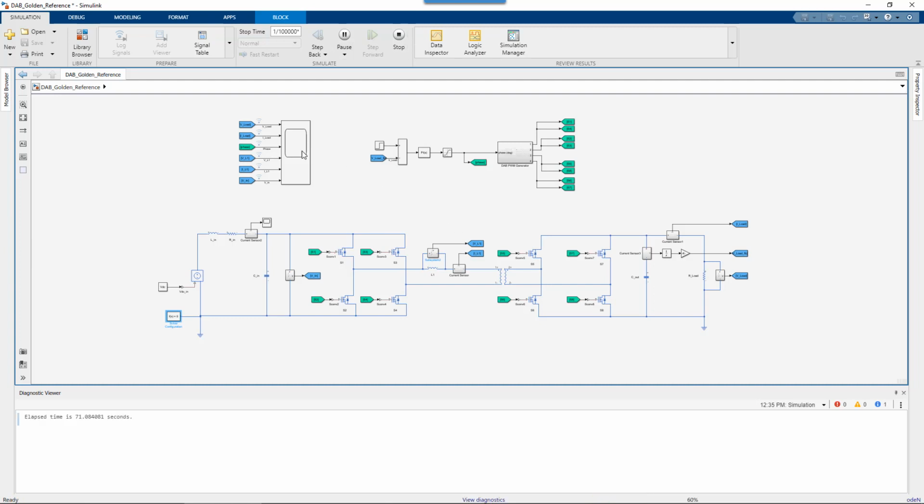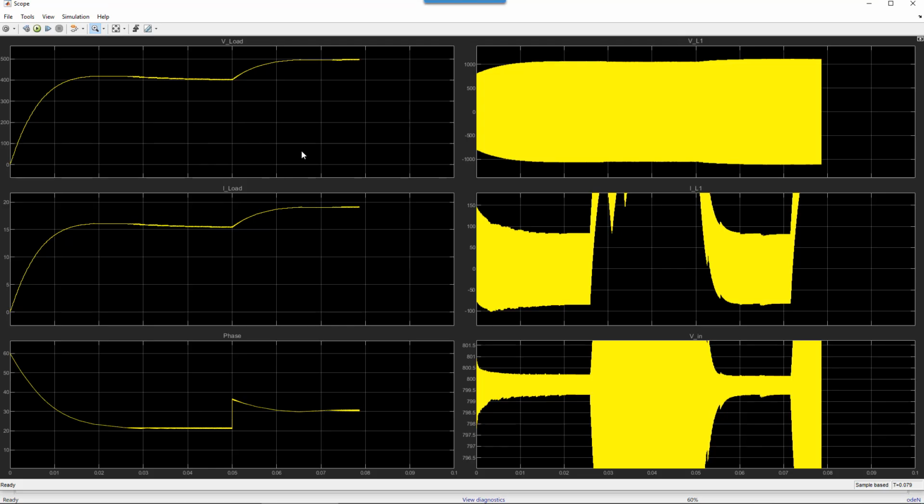So this is taking much longer. And you can see you've got these weird artifacts. If you see these weird artifacts with a variable step solver, that's when I was talking about, go try turn on adaptive zero crossing. Because you really shouldn't see something like this.